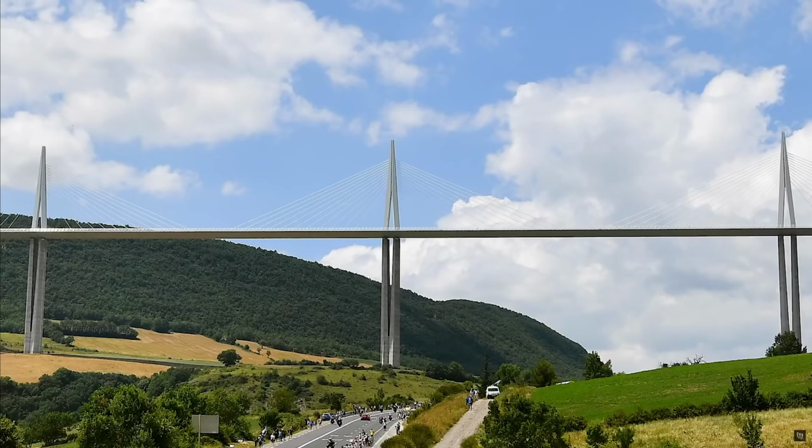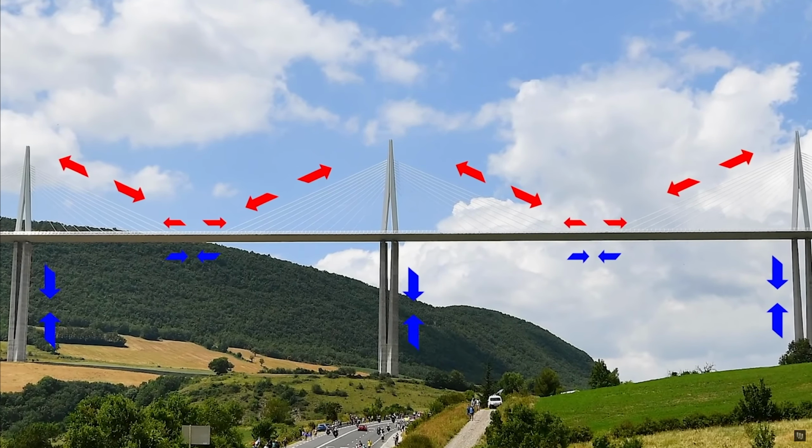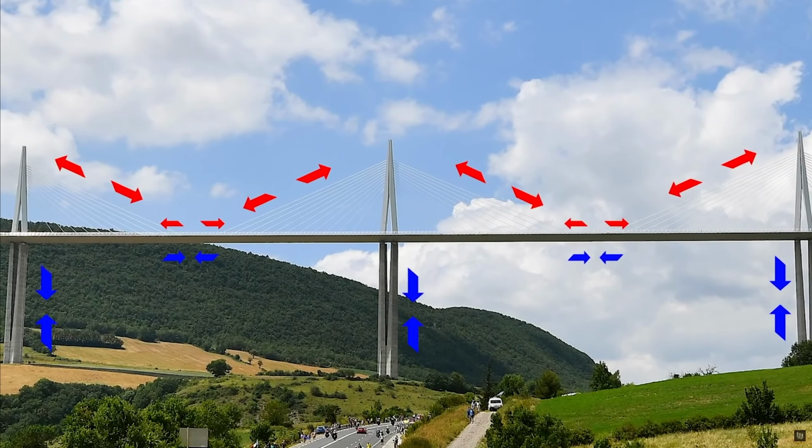And so because you don't want to have so many supports, also when you're building a bridge across a large body of water, the energy and the effort it takes to drill piers or piles down beneath the surface of the water and to build these supports makes it more of an incentive to have fewer supports, right? And because we want fewer supports, we're then going to consider a bridge type that can allow us to have longer spans. Hence the suspension bridges, and even more so the cable stayed bridges, become an attractive option. Not to mention it just looks cool.